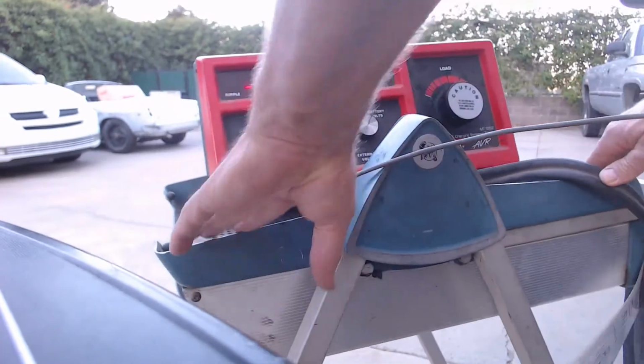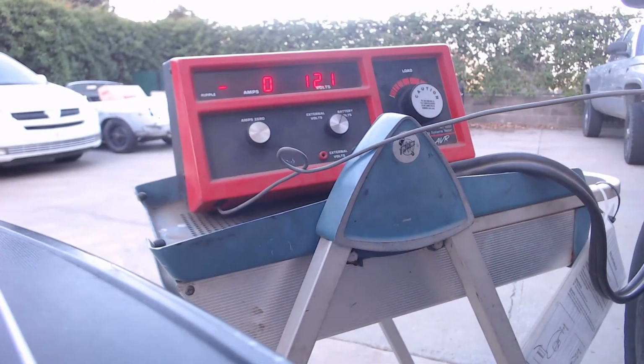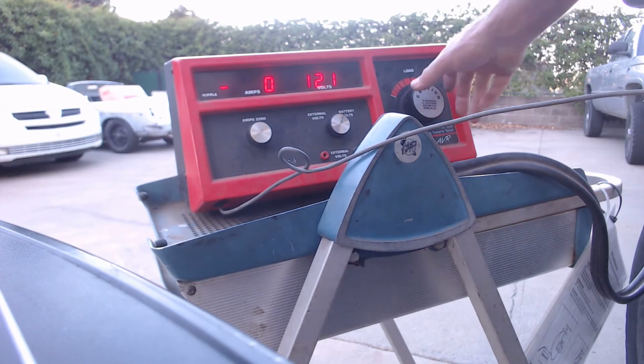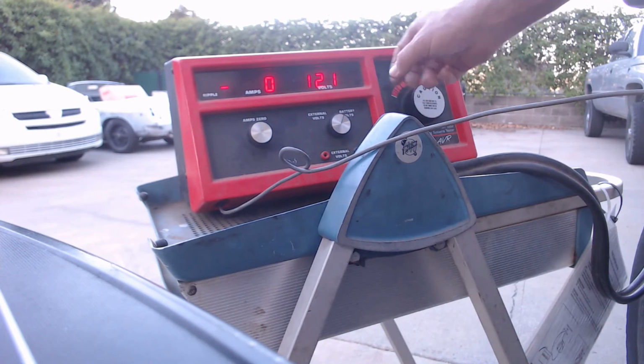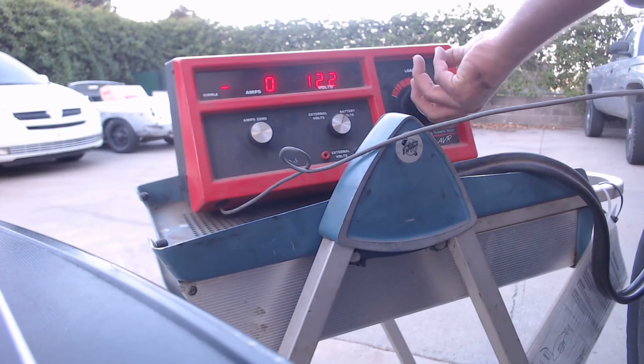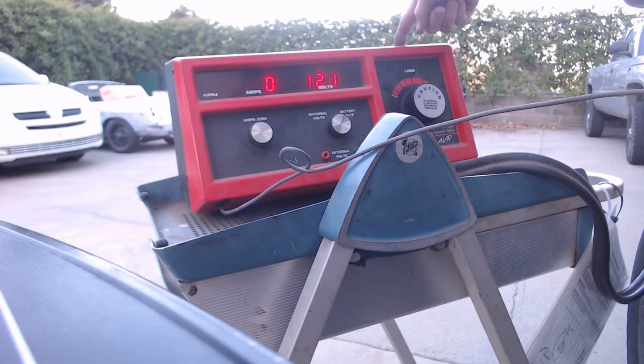And so what's going to happen is I'm going to put a pedal depressor to the floor and onto the gas pedal, and I'm going to get it up to 2,000 RPM. Then I'm going to come out here. This is going to be reading about 14.4 volts. I'm going to turn this guy up, which is a load. This loads the alternator. This is going to suck power and expend it on what's called a carbon pile.